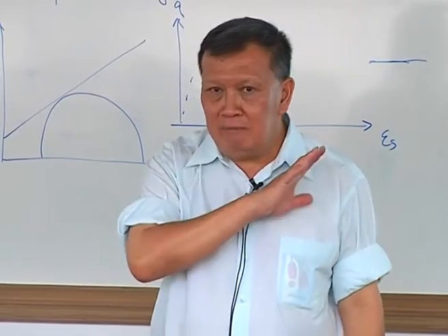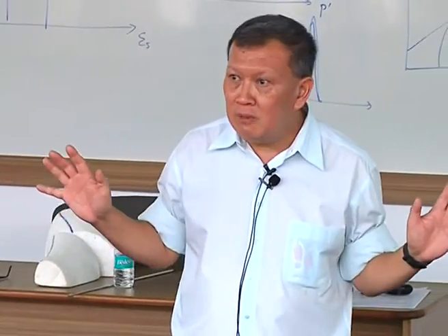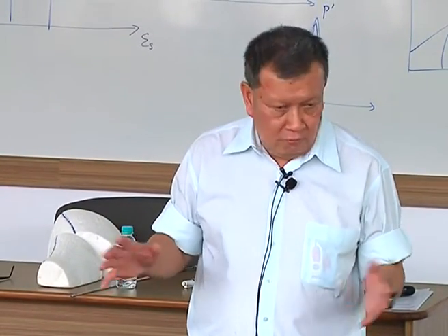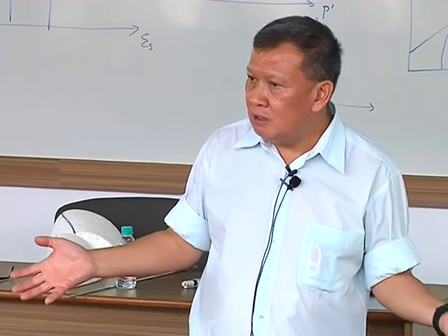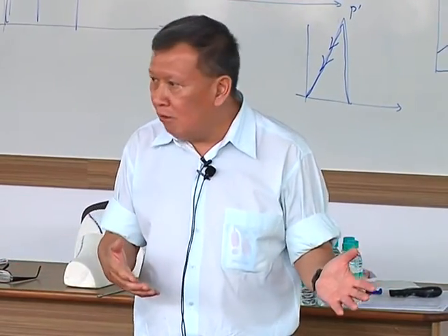And I can show you an example. The Fort Canning Tunnel is a classic example. I used the simplest Mohr-Coulomb. I used method A. I even went up there to justify to the government people. I said, why do I use this method? I said, look, this is okay. This material is fine. It's not soft soil. This material is fine. You look at the A parameter, it is 0, no?